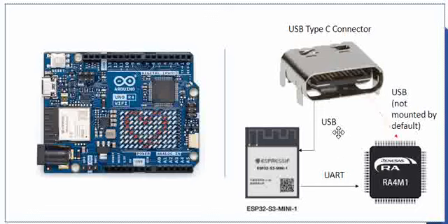So you can look at the schematic. At first look, people would have thought that there is a separate USB to UART switch which connects directly to RA4M1, and further RA4M1 communicates with Espressif. But actually the internal USB to UART switch of Espressif helps to connect to RA4M1, which is a very interesting thing in the Arduino Uno R4.